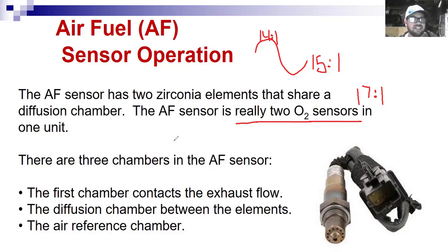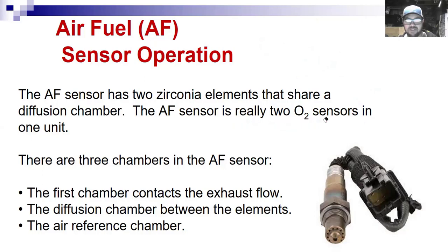And these things tend to stick in there because they run so darn hot. I've had several cars where you go to replace an air fuel ratio sensor and the threads in the exhaust manifold get stripped out because these suckers just run so darn hot. Okay. But they do have a lifespan to them, like an oxygen sensor. And so it's not outside the box at 80, 90, maybe 100,000 miles to have one of these guys fail on you.